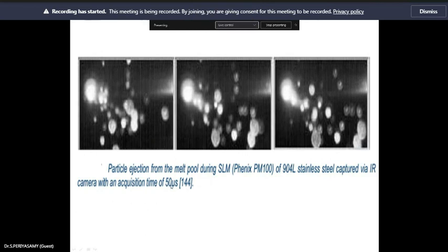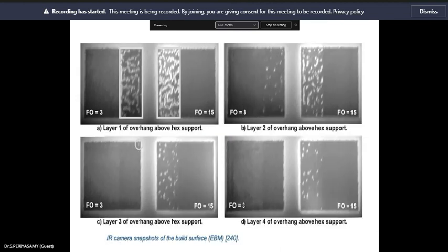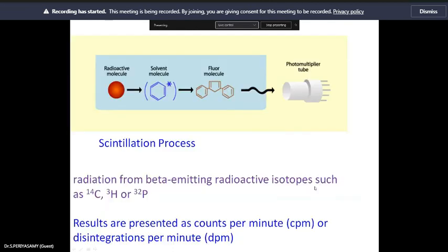There is the ultrasonic consolidation. Ultrasonic consolidation is another method in additive manufacturing. In that, layer by layer, they use the same ultrasonic sources. We can do the layer by layer joining. So in that, delamination means the layer will be detached from the previous layer, or the top layer from the succeeding layer. The layer will be detached, in the sense you can get the delamination. The delamination you can also easily identify using the scanner.